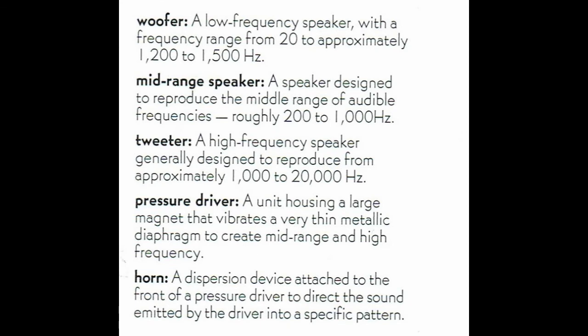Speakers work most effectively and efficiently when they are designed for a relatively narrow frequency range. Speakers are generally classified as low frequency, or woofers, mid frequency, mid-range, and high frequency, tweeters. Almost all woofers are cone-type loudspeakers. Mid-range speakers and tweeters are also made with cones, but loudspeakers for live performances are typically manufactured using pressure drivers and horns due to the high sound pressure levels and carefully controlled coverage angles required.